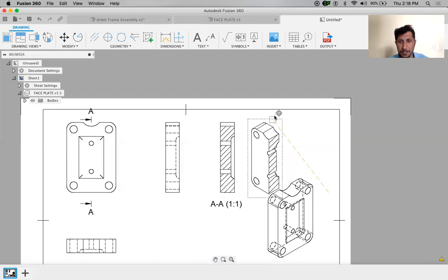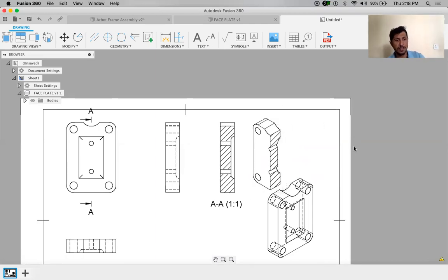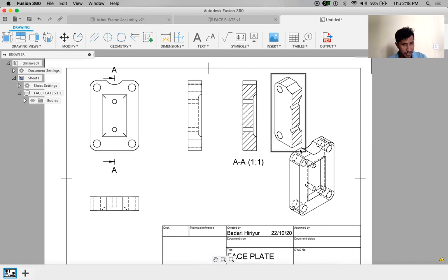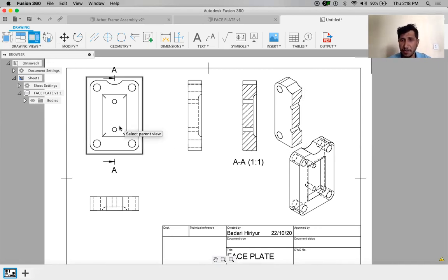So that's the best point. Sometimes, as I mentioned, if the design is very complicated, in such case, you can use this function to create a nice 2D drawing which will explain the complete structure of your design, right? So this is section view, and as I mentioned, whenever you create section view, you also have an option available, distance and also slice. Depending on that, you can create the section view with the provided distance also.